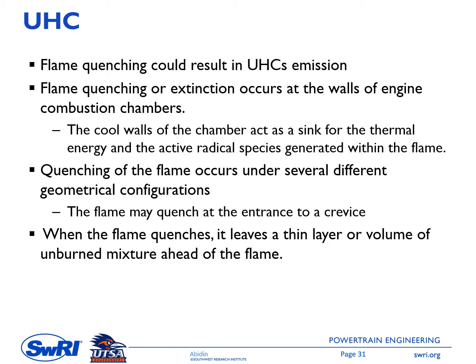Flame quenching could result in unburned hydrocarbon emission. Flame quenching, or extinction, occurs at the walls of the engine combustion chamber, and this is due to the lower temperature of the wall. These cool walls act as a sink for the thermal energy and the reactive radical species generated within the flame. Quenching can occur under several different geometrical configurations.